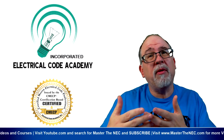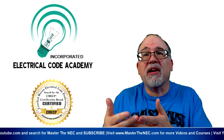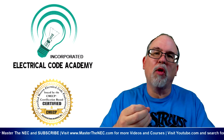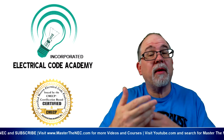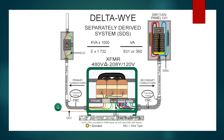You have some allowances there for sizing these conductors. Ultimately, at the end of the day, I need to make sure I've got conductors that can handle the load, but we use these tap rules because we don't always have overcurrent protection at the location of the tap. Looking back at the graphic, the secondary conductors are these here in our example. Since we don't have overcurrent protection here, we have it down here, and that's governed by certain rules, secondary 10-foot rules and secondary 25-foot rules, which tell you how to size these conductors. But just for today, since this is a 300 amp overcurrent device, I want to make sure, and I will remind you of something now.